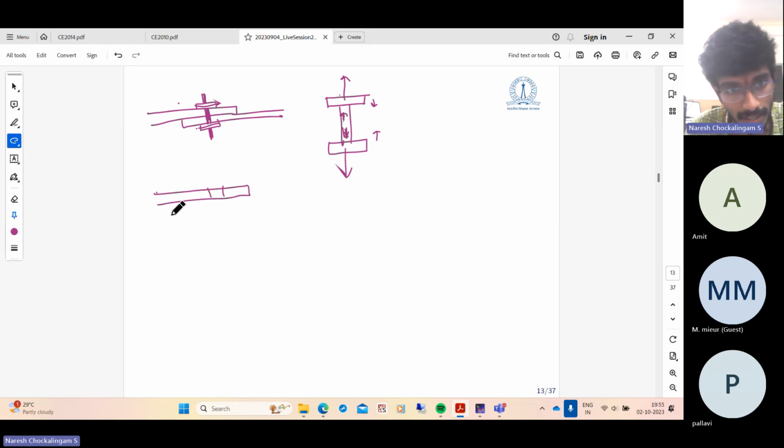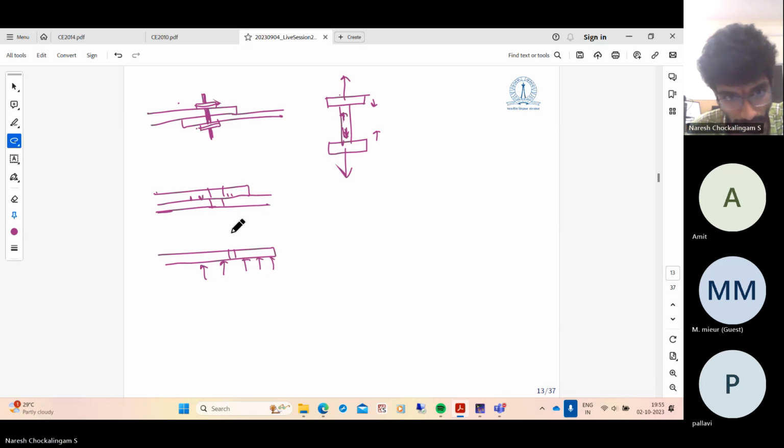So we have removed the bolt. This is the slot. The plates are pressing against each other with some compressive force. And if you draw the free body diagram of one plate, there are some compressive forces here over the interface. What will that cause? That will press them against each other, and these surfaces are not ideal, they are not smooth. So when it is not loaded, we just have a compressive force.